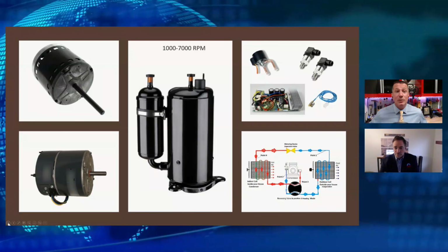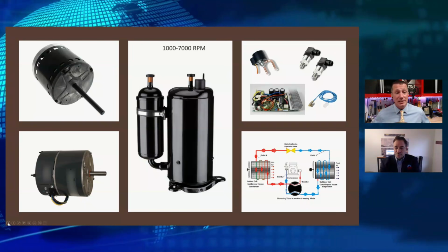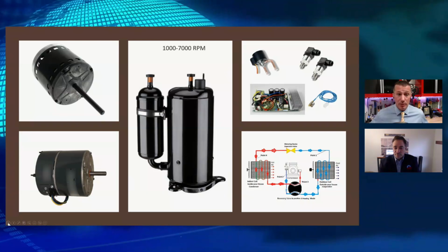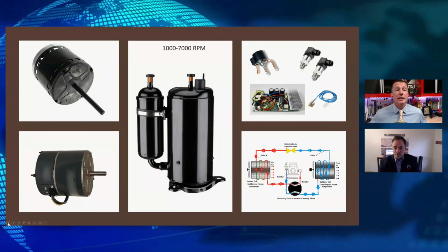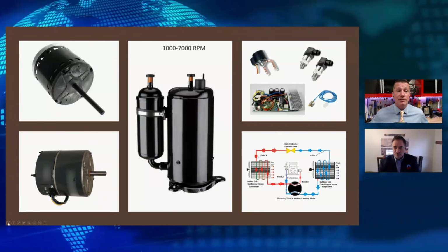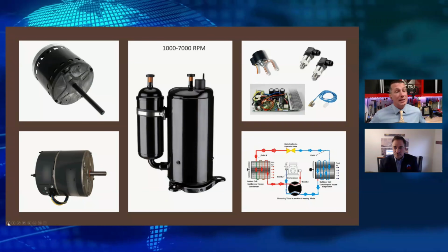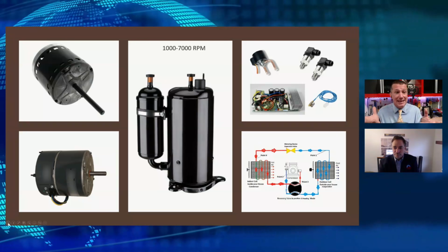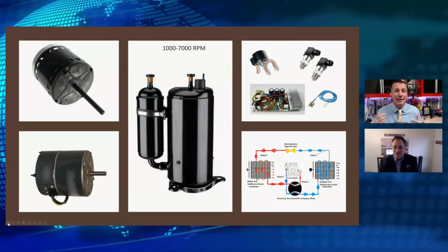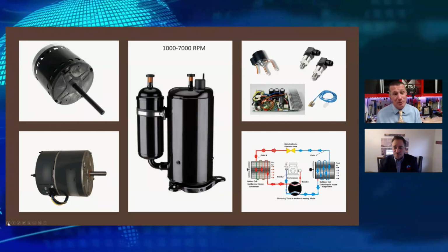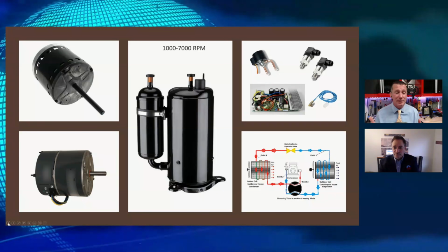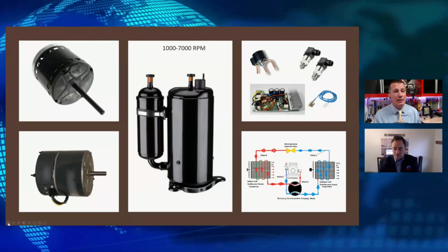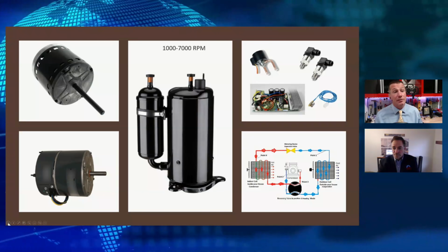And we have seen that. We actually saw that this year. We've seen pieces of equipment that were not properly installed for their climate zone, so capable of producing ultra-low temperatures, but were required in the installation manuals for an additional drain pan heater that was not installed, and therefore that piece of equipment was having failures because it was ice damming in very low temperatures. And what's that going to do for the product name and for the product quality? It's going to ruin that. So we have to make sure that we look in our manuals to validate if our piece of equipment requires a drain heater in those lower temperatures. A lot of them do.